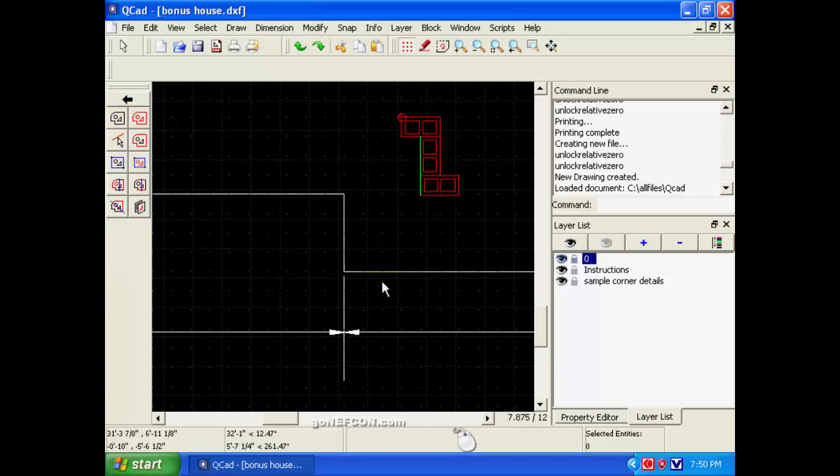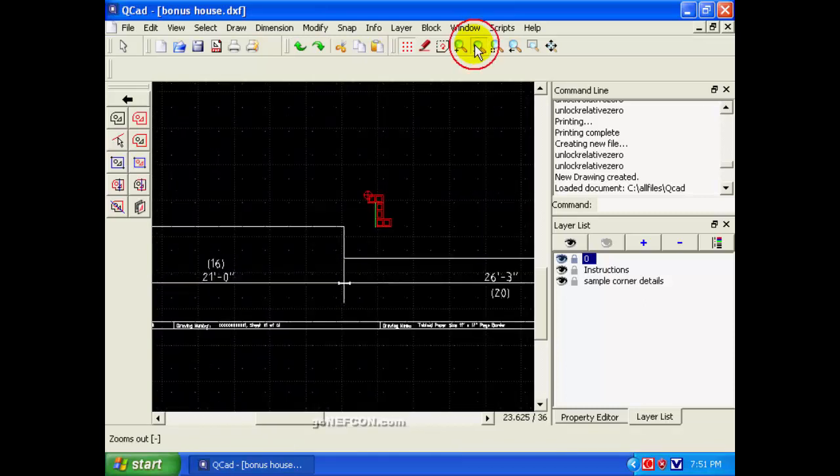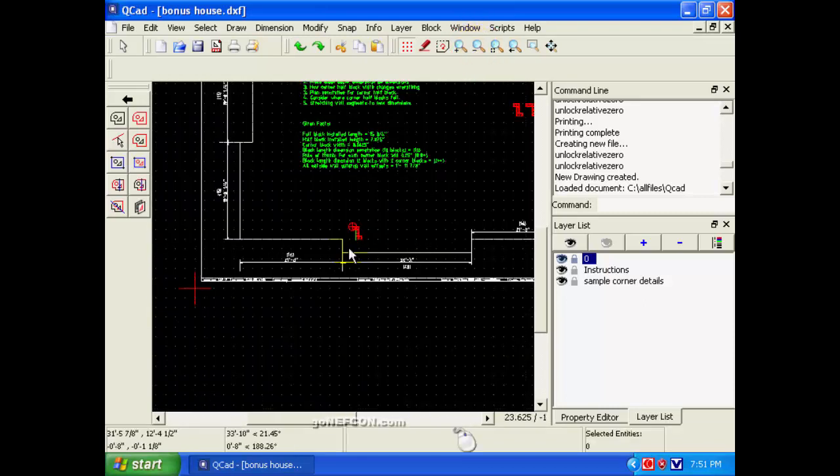So what we're going to do, we're going to now fix this wall. Right now the dimension from here to here is 31.5 inches, when in fact it should be 23 7/8 inches. So the difference between those two numbers is 7.625. So let's back out a little bit here. We're going to move this wall segment 7.625 inches up. And we want to take with it these dimensions because the dimensions haven't changed in horizontal dimension.